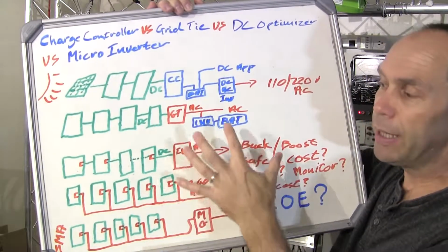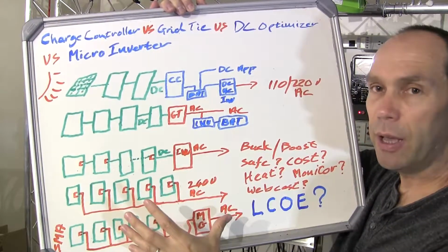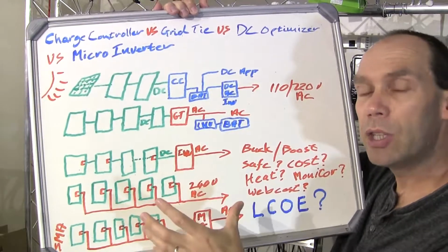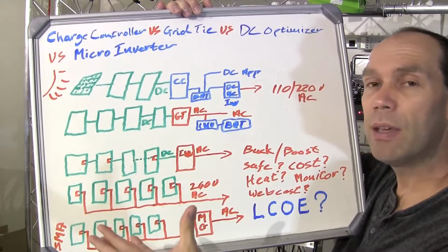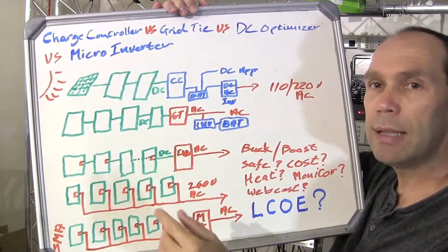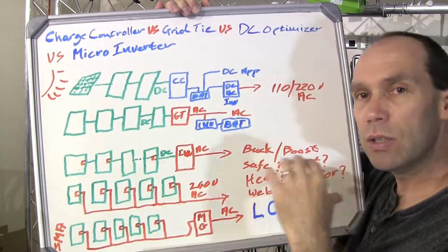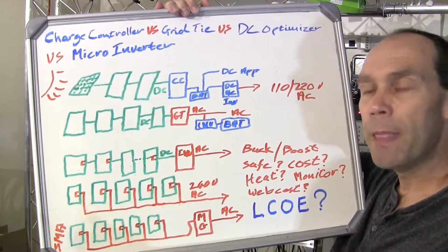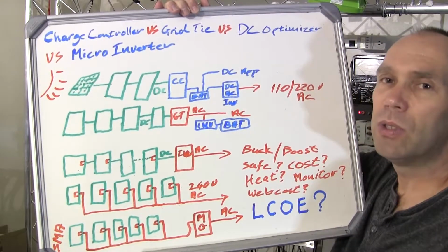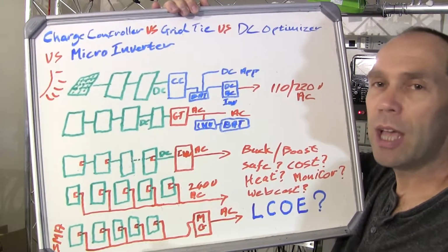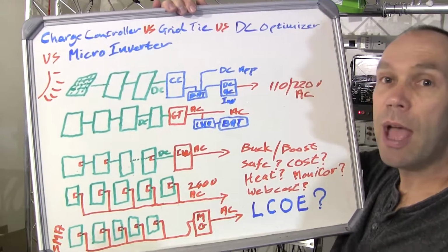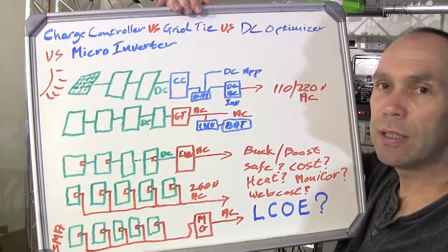But what you ultimately need to do is take the complete cost of a year, the complete power production, say over 25 years, and then normalize that, or level it, across the entire investment. That's of course very difficult to do because each installation is going to have different energy production and different challenges in terms of the installation.